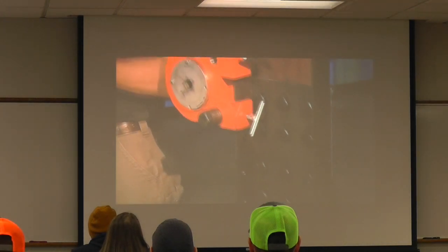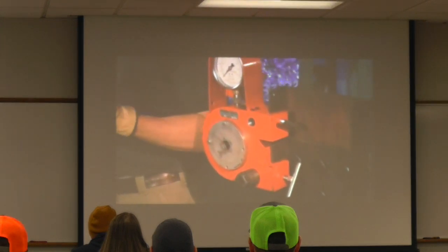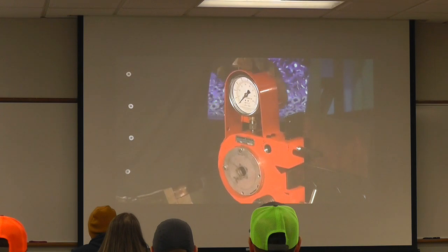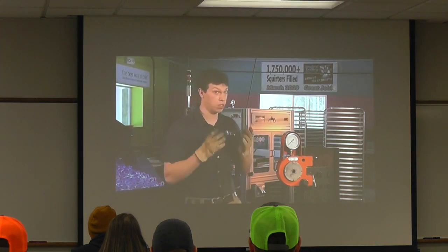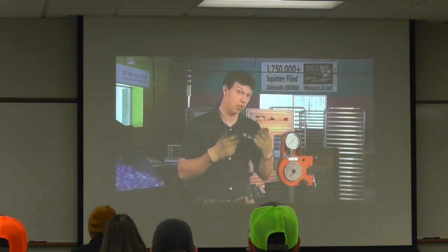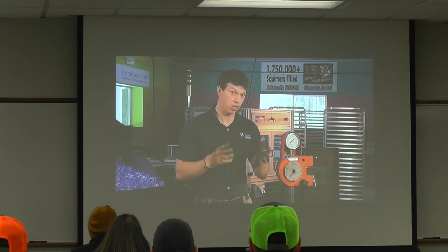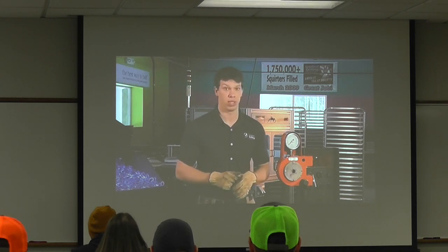Now the first thing we're going to need to do the pre-install test is a calibrated hydraulic load cell designed to measure bolt tension, such as our Skidmore Wilhelm here. Now it's also very important that your Skidmore or whatever hydraulic load cell you're using is within its calibration date. Otherwise, all these tests we're going to be doing are null and void.